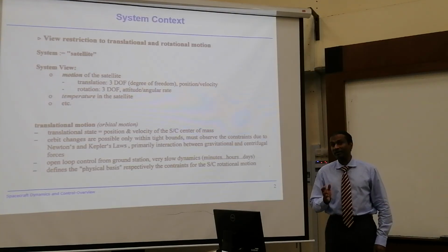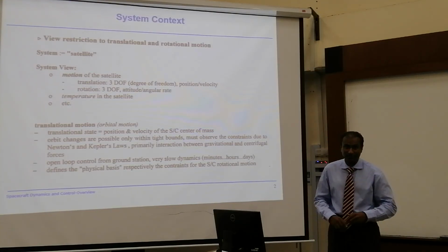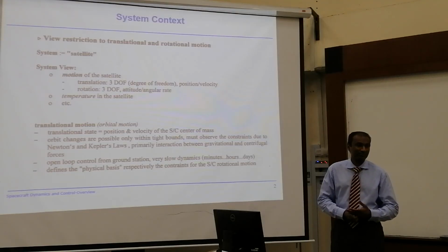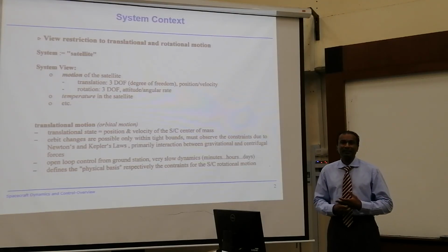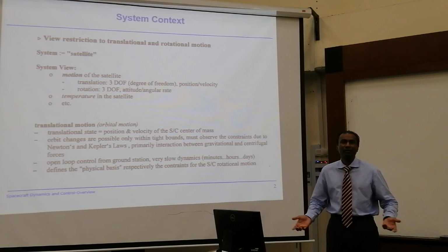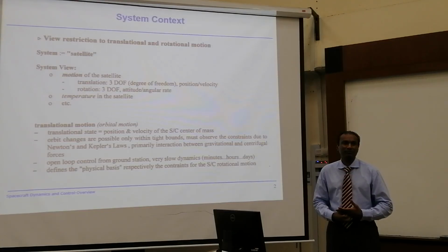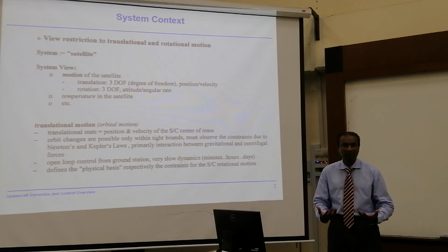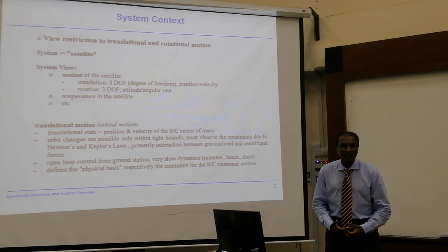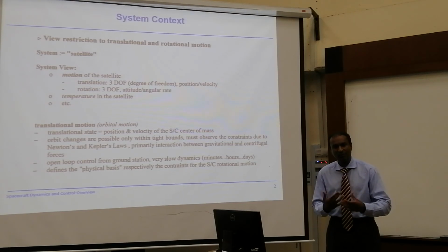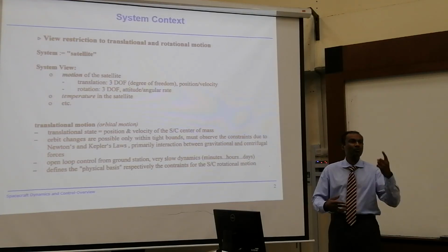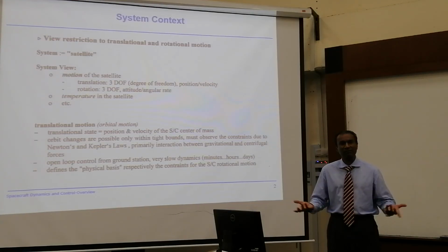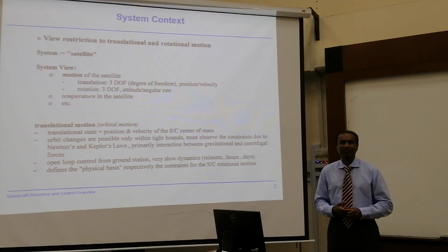Even in orbital mechanics, you learn that some corrections happen once a year. For example, inclination correction. Not often. We don't do that often because we can't afford it. In fact, the nature of those disturbances is also not severe every day. The cumulative effect over a year, yes. Then we do one correction a year, or two corrections maximum.